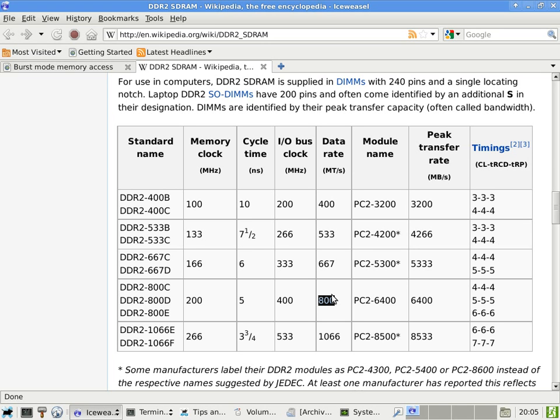Yep. Even at such short distances, if the length of those traces is off by even a small amount, because of the speed of light transfer of electrons, you can cause variations in off by 1 bit out of 8 in a parallel transfer. Yes. But the problem is not only the length itself, it's not just the time itself, it also has to do with the inductance and the capacitance of the lines. If the length of different lines are different, then the inductance and the capacitance of those lines will also be different.